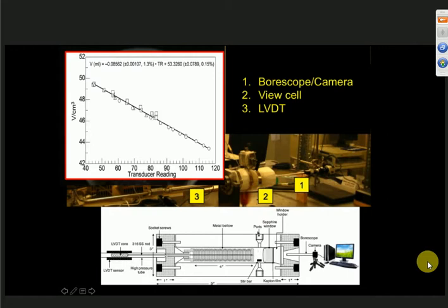So what you do is you put in a fluid of unknown density, where you should know the exact mass to milligram accuracy. Once you take it to a certain temperature and pressure, based on the position of the sensor, you can read the volume of the cell. So you get the volume and you know the mass, and mass divided by the volume gives you the density. And you can do this even at high pressures, and high pressures here means really going to 3000 bar.